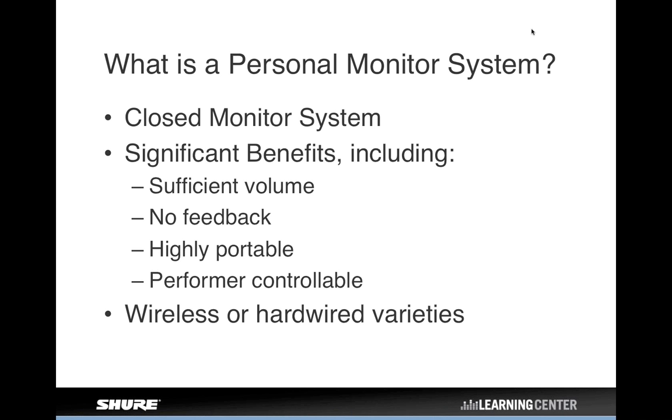And then as far as affecting the environment, when you go to in-ear monitors, now you shoved the loudspeakers into your head and isolated them there so you can hear whatever you want without contributing anything else to the acoustic environment. And that includes the audience too, because wedge loudspeakers still have spill that happens into the audience area that affects what they're hearing too. And then again, you can now personalize your mix more, because what's going on in your head is what you want to hear, because you're hopefully using an isolating earphone that is reducing the ambient sound level of everything else going on the stage, so that again, you're not being affected by what else is going on around you. You're kind of in your own little monitoring world there. So there's some significant benefits to this.